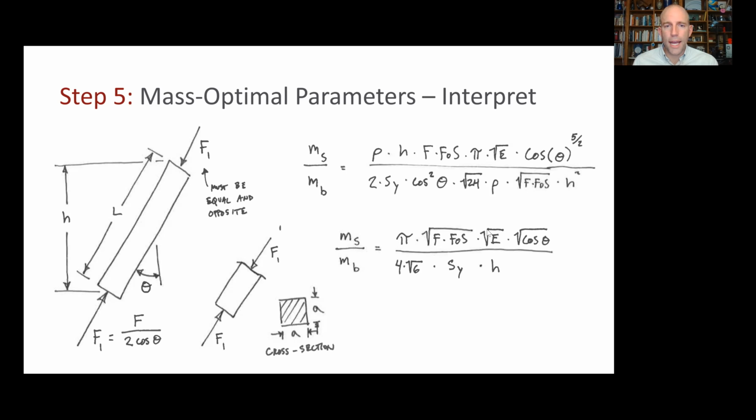If we've got a high elastic modulus, that means that the material is stiffer and it's springier and less likely to buckle. And in those cases, the stress dictated size is likely to dominate. And for very similar reasons, if the yield strength is really high, then you need less cross-sectional area to avoid yielding. And because the cross-sectional area gets smaller, then buckling becomes more of an issue.